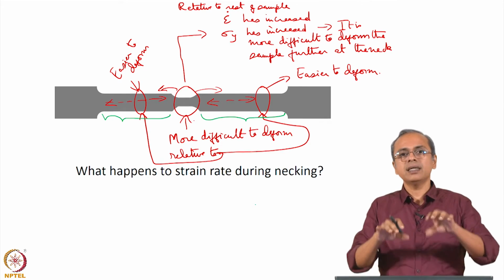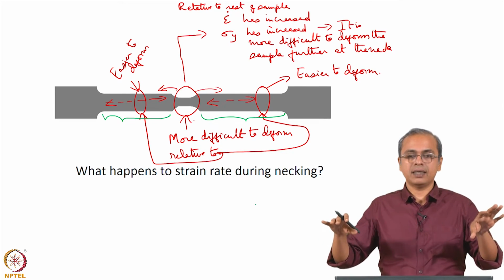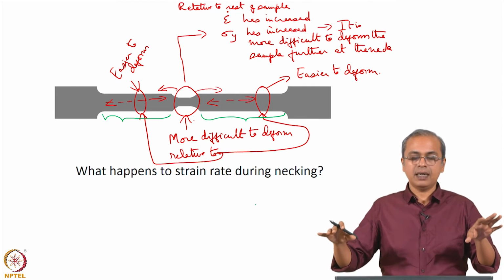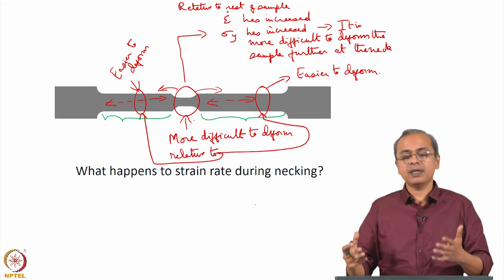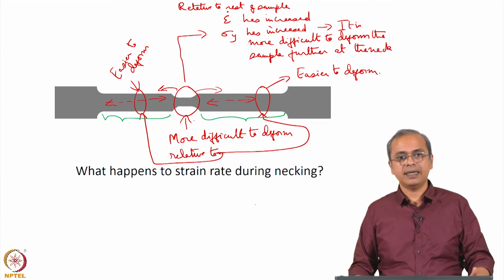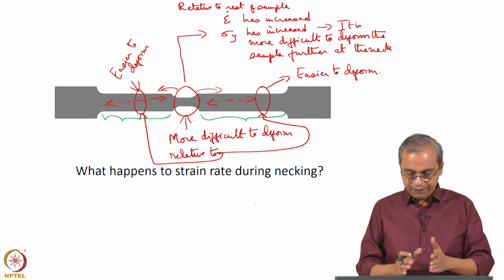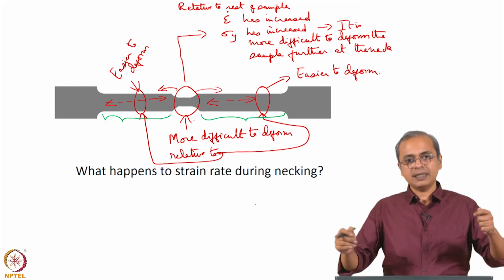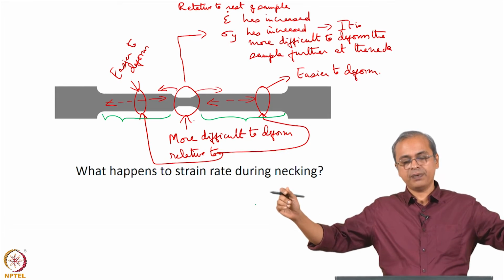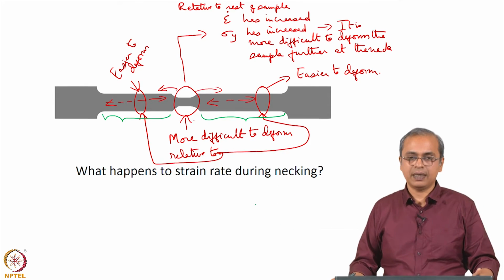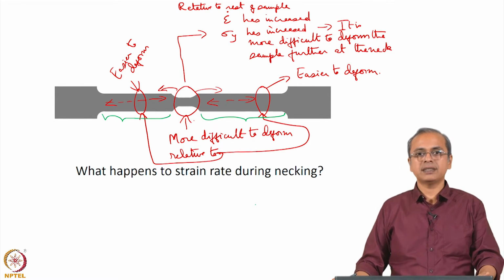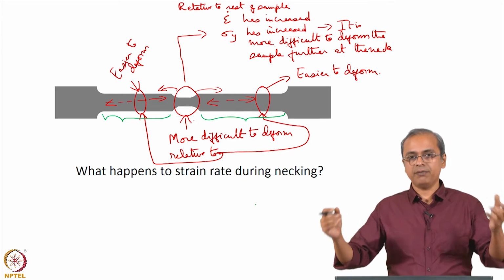So this is the reason why these materials that show superplastic behavior show that behavior as a direct result of this strain rate sensitivity index. And once you consider this concept, you understand why this material keeps expanding over a very long extent of expansion before it finally fractures.